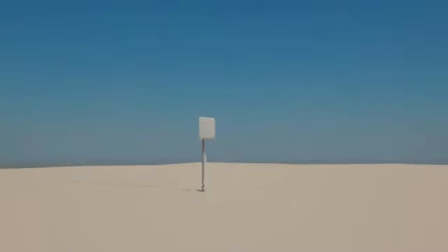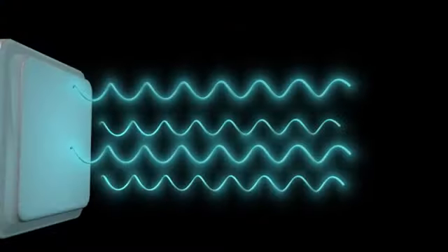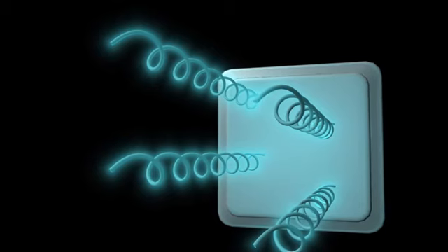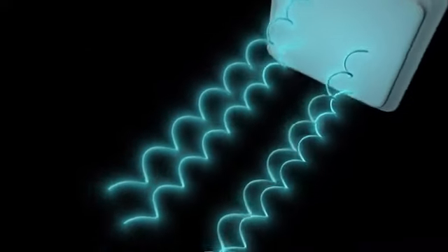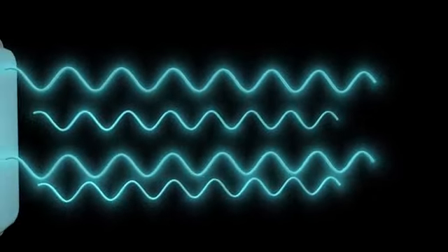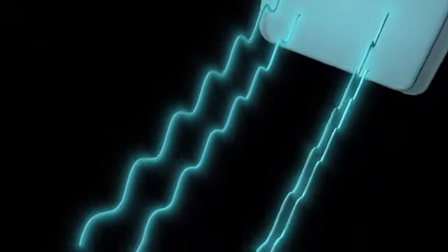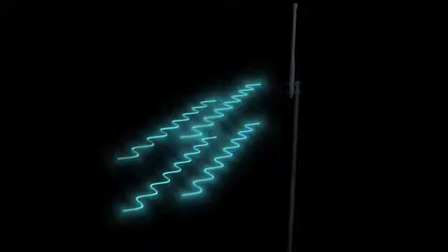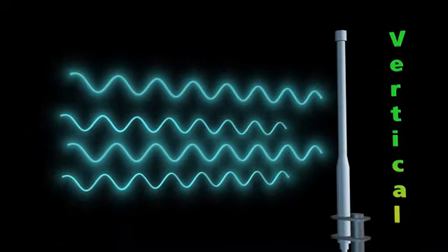Antenna polarity refers to the direction that the electromagnetic field lines point as the energy radiates away from the antenna. In general, antenna polarization is elliptical, meaning that the polarization of the radio waves varies over time. The simplest and most common form of this elliptical polarization is simply a straight line, or linear polarization. This is where the radio waves oscillate in only one direction. The direction can be either vertical or horizontal polarization. Of the transmitted power that reaches a receiving antenna, only the portion that has the same polarization as the receiving antenna polarization is actually received.